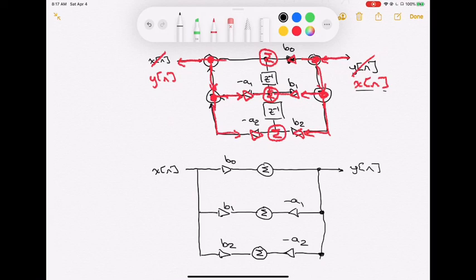What's in the middle? Well, those are our delay blocks. So we're going to have a delay block here, z to the minus 1. Z to the minus 1 is just a piece of physical memory on my PC, remember that? And then these guys are going to chain up. They're going to go through something like this. Okay, so this should be a completely equivalent structure to what we had before.